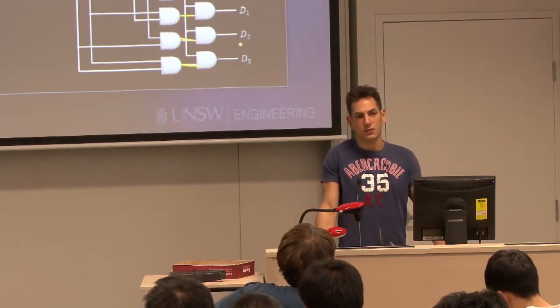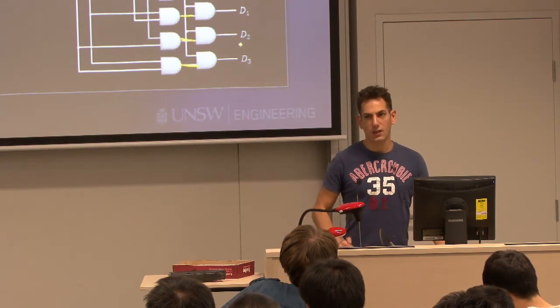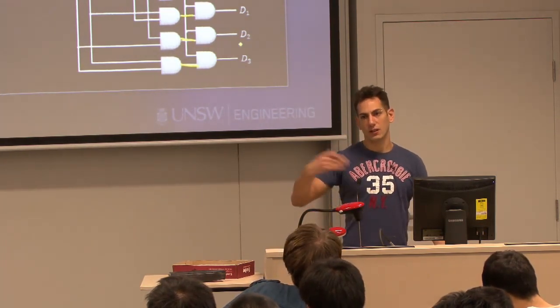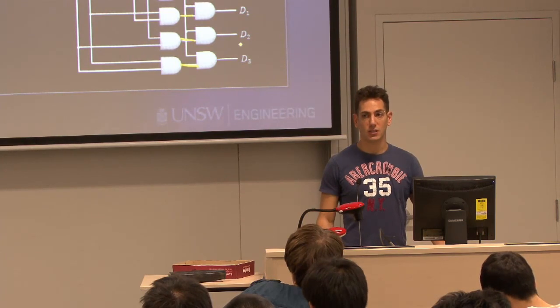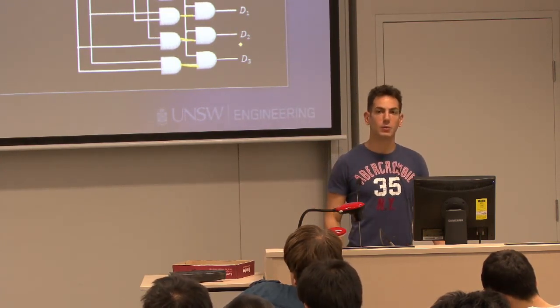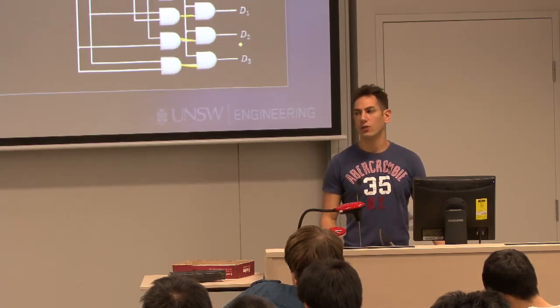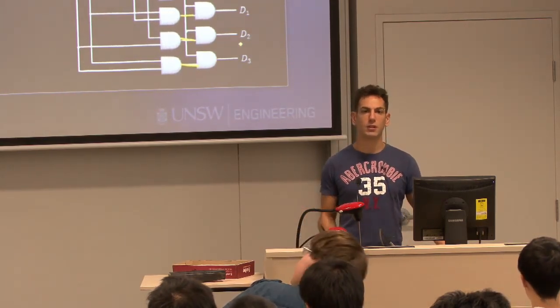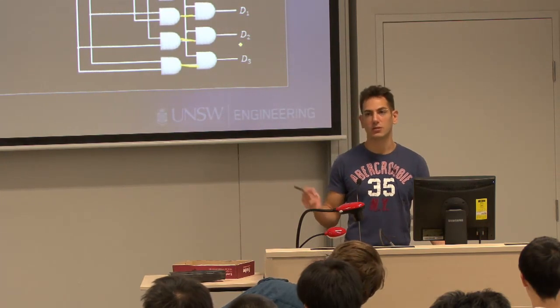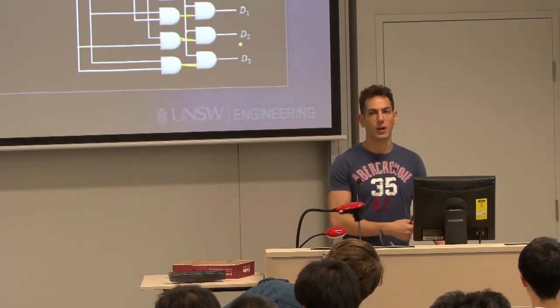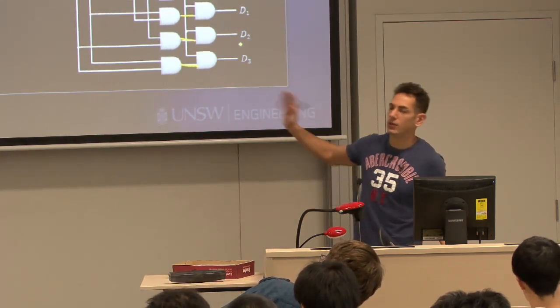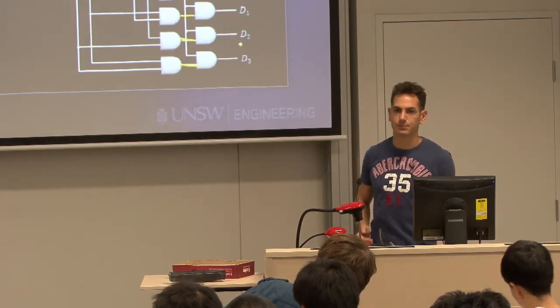If they're not of type wire, because I said there are different types of nets, you can override this default and define them as something else. We will see, on Tuesday, that we override a few of those, well, the outputs usually, and make them registers rather than wires. But for now, if you don't declare anything else, they are wires.